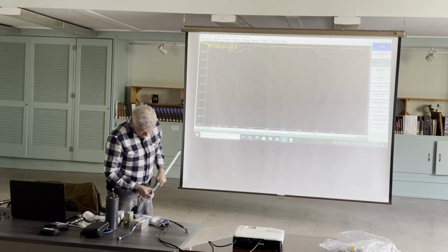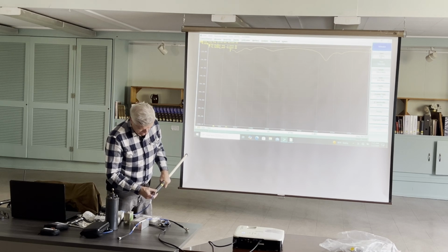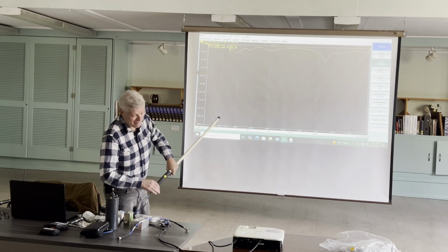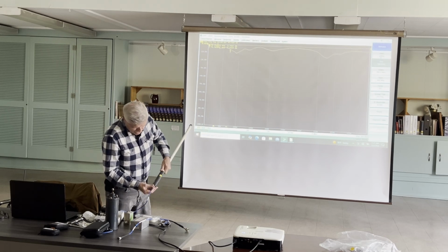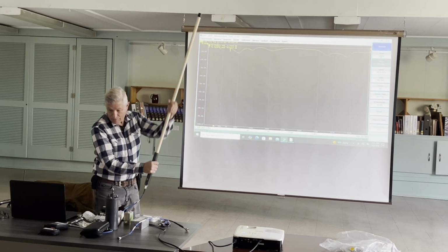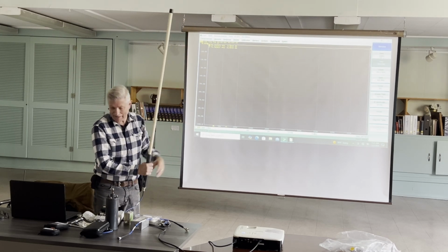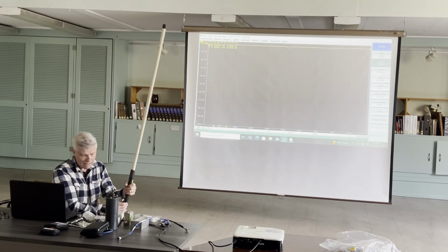Now, of course, when you measure an antenna, especially a VHF or UHF antenna, you don't want to do what I'm doing. It wants to be on a pole with no obstructions near it, because you can have reflections. Just putting my hand, look what's happening. I can tune the antenna with my hand. So now that's return loss.